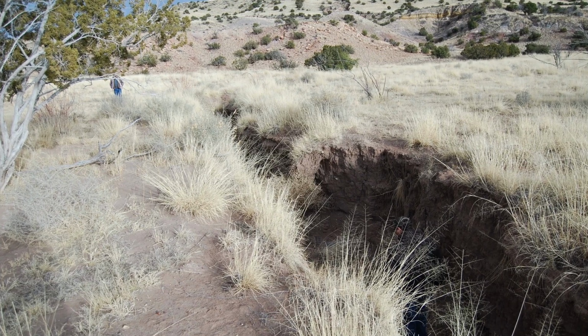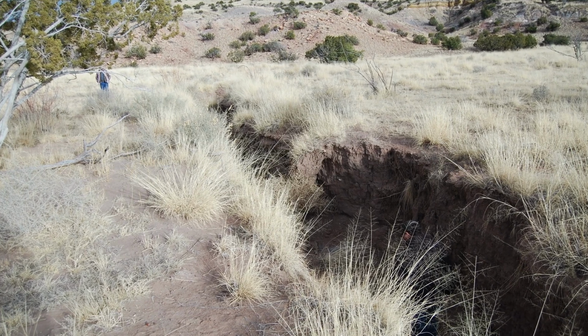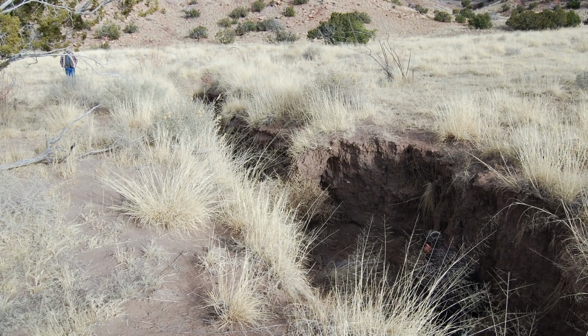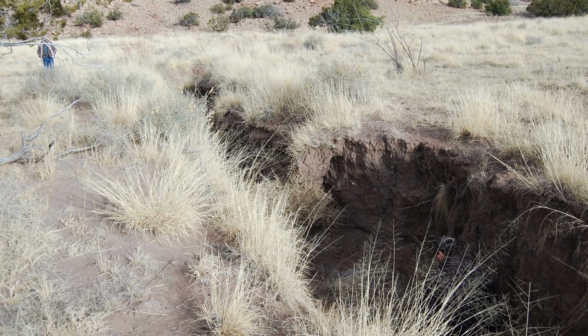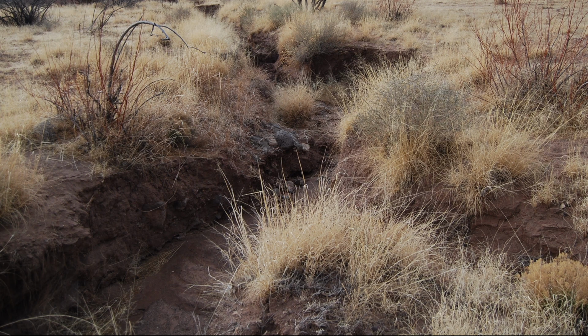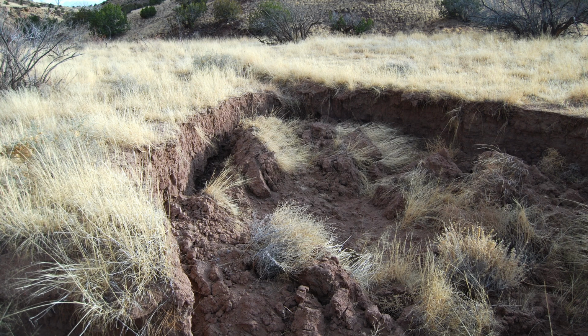The head cuts were causing a deepening and a widening of the stream that was flowing out of the pond. The head cuts were moving uphill towards the pond and would soon enter the basin and drain the pond forever. Water flowing out of the pond had eroded a gully. Just downhill of the gully, we found this head cut in the spillway that was causing erosion.